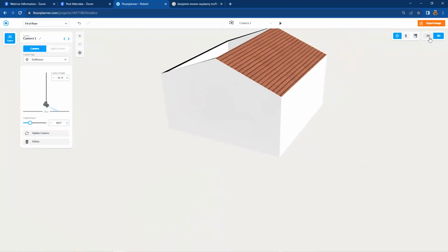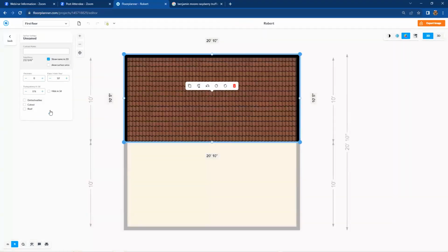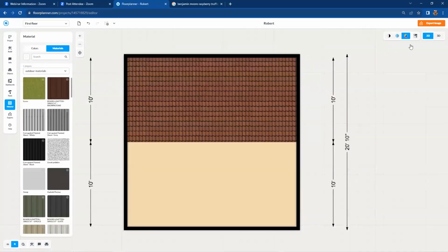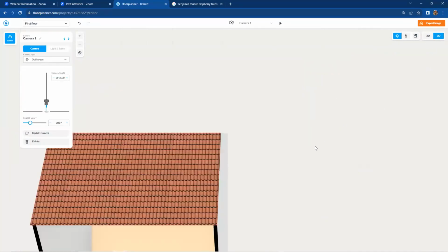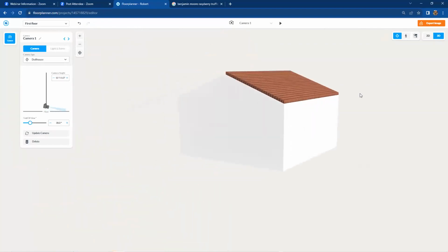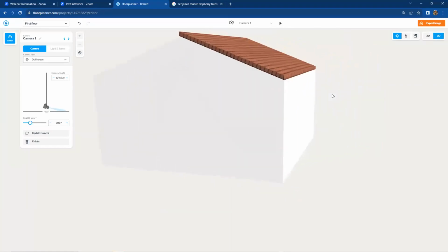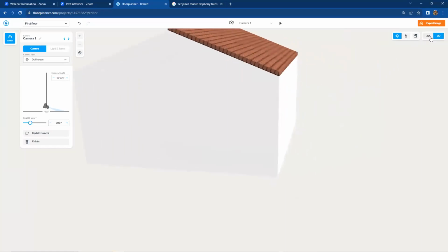You know that it's going to render even better, but it's a little thin. Surfaces, not only will they accept materials, now have a new feature that you can select them and go to the settings of the surface and you can give it thickness and extrusion. So if I say I want to make it 5 inches thick, hit enter. And as a roofing material for Spanish tile materials, it is now much more realistic than it was previously because we gave it some thickness. Of course, again, preview image, you know it's going to render even nicer.